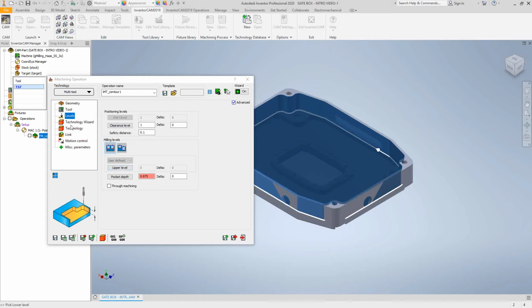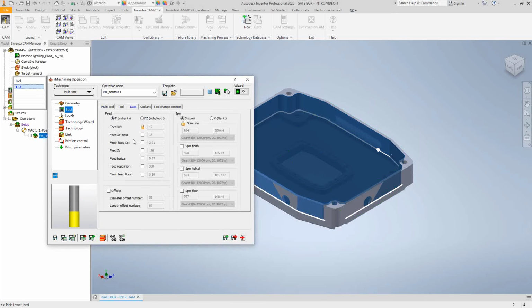The workflow of 2D iMachining is very similar to pocketing. As we did here, you saw geometry, tool, and levels. Now we need to decide feeds and speeds. Well, with iMachining, feeds and speeds are actually going to be locked out because iMachining is controlling that. It's calculating those based off your machine, your material, and now I've given it the dimensions of my end mill. So all three bits of information go into the calculation of iMachining.